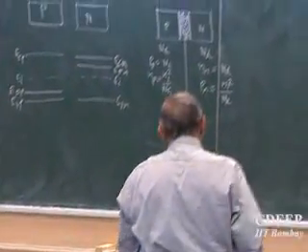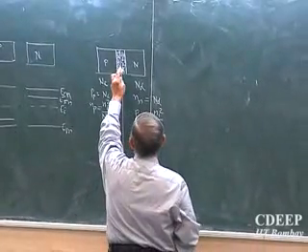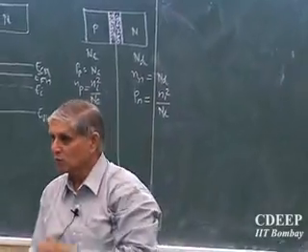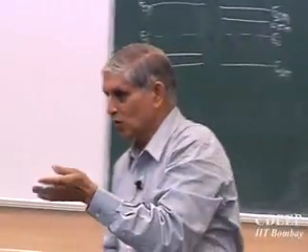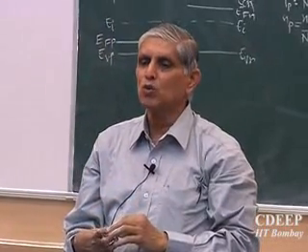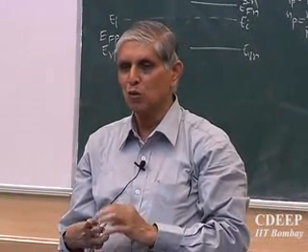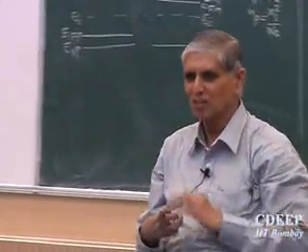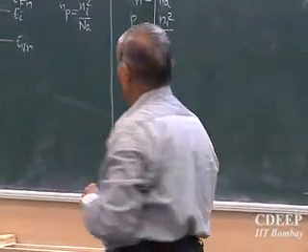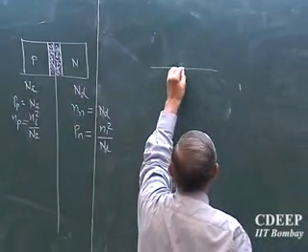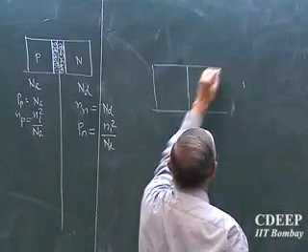Right now we assume there are no electrons and holes in this region. Those electrons were already gone, and on the P side the holes are already gone. So in this region, there are no free electrons and holes. That is the assumption. In reality, how much can we find? Very small compared to the rest. So we say this is equivalent to something like this, only this portion I show you.